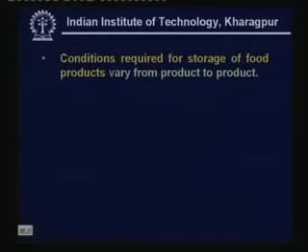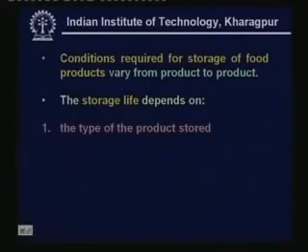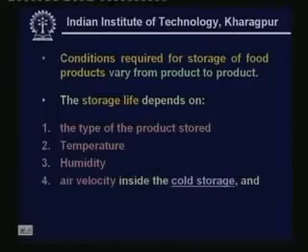Now, what are the conditions required for storage of food products? It's not that all the food products require the same conditions for storage. It's not so. Every product has optimum storage conditions, and the storage life generally depends on the type of the product stored, the temperature at which the product is stored, and the moisture content and humidity inside the cold storage, and air velocity inside the cold storage. So these are the 4 factors.